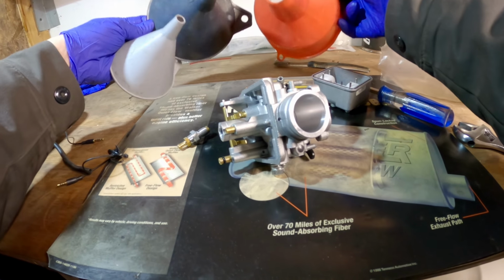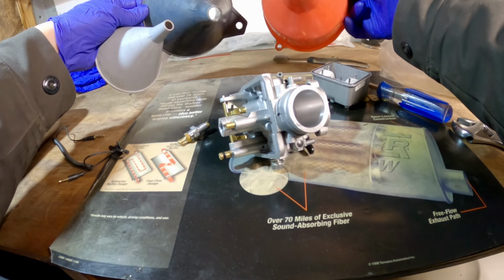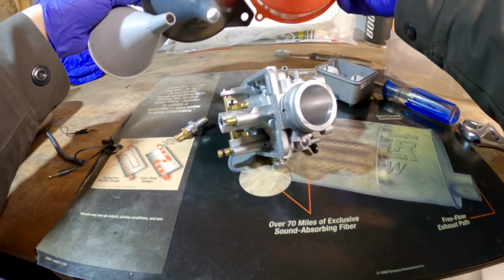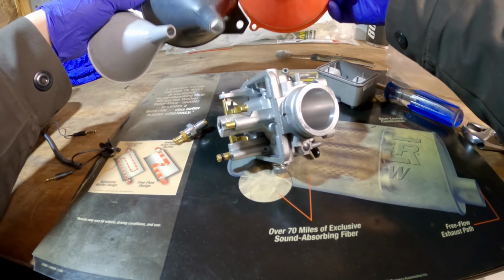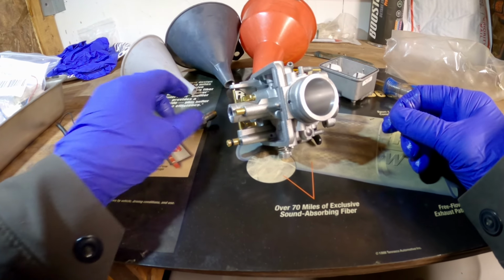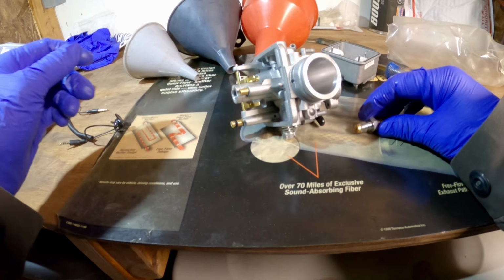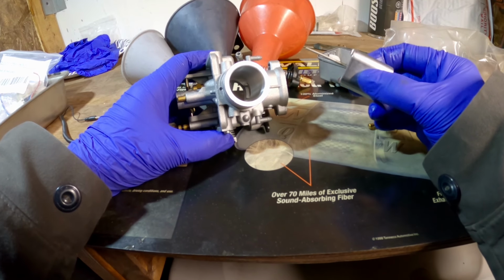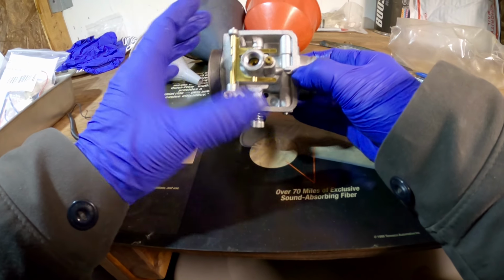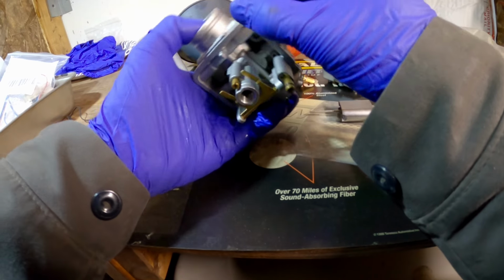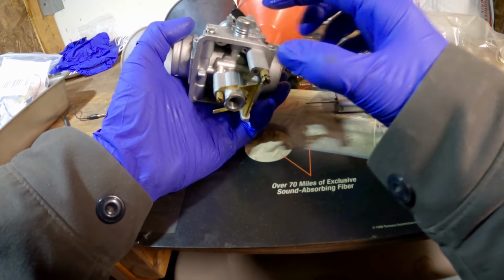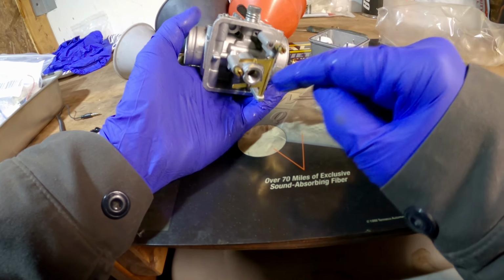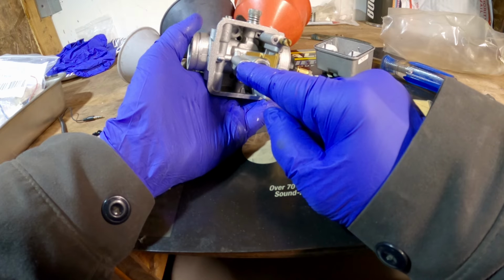We're changing flow areas, effective areas of flow, and then all the tools are out there, and there's the tuning charts to get you in the correct area and help you choose which one you need to adjust. Do you need to adjust the main jet for wide open throttle? Do you need to adjust the needle, taper, clip position, straight section diameter to get your mid-range? And then adjusting the pilot jet based on your fuel or air screw authority. So if you reach the limits of your fuel or air screw, depending on your carb, that tells you if you need to adjust your pilot jet up or down.